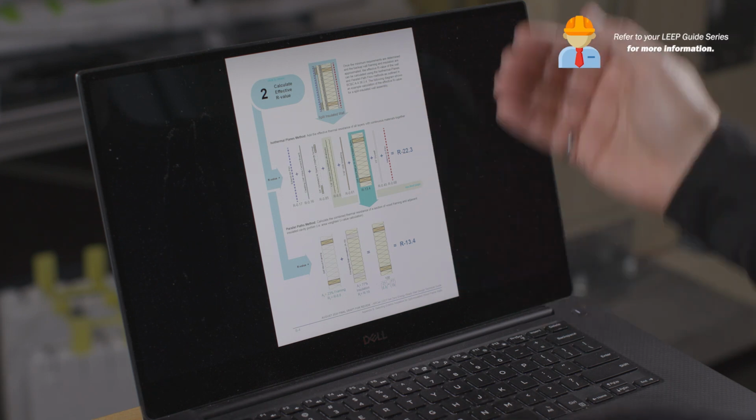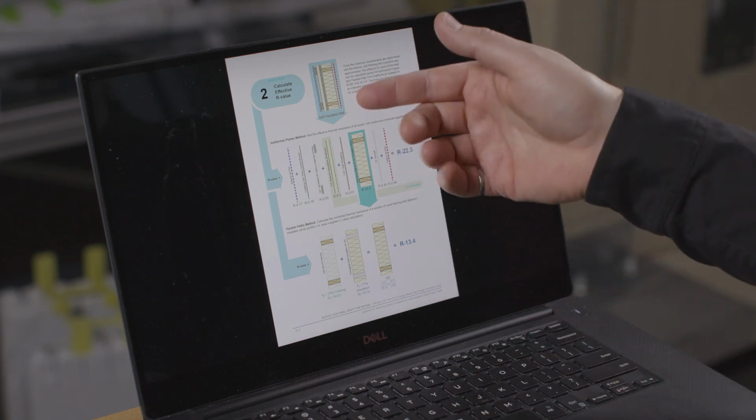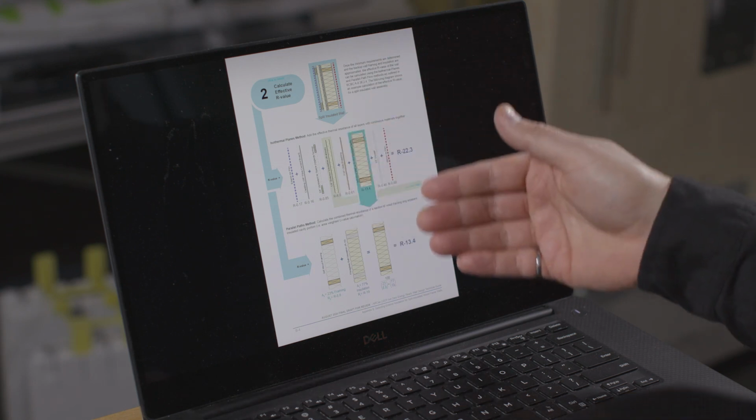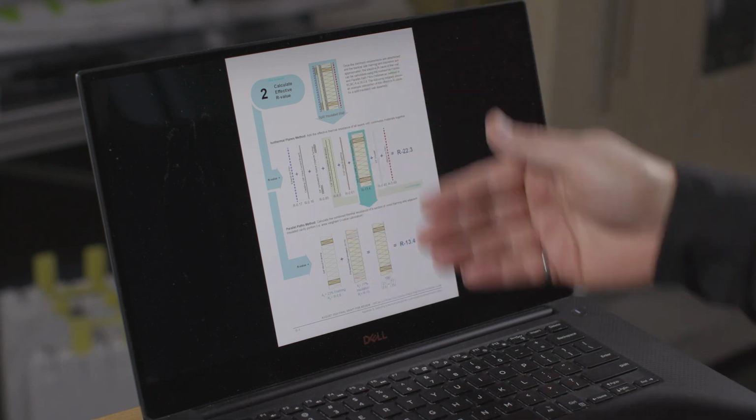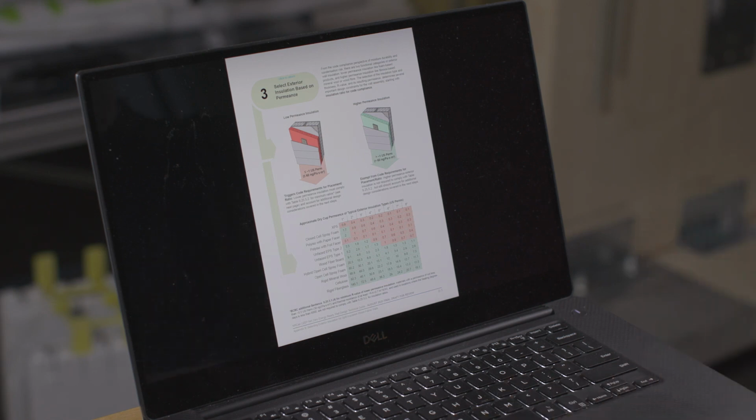Once you've sort of figured out a thickness of exterior insulation you need and type of insulation, you're going to now calculate the effective R value. You're going to use parallel path calculation in 936. You don't have to actually do the calculation here, but this is how it's done, where you've calculated the R value for all the pieces of the R value, including the framing factor, added in with the exterior insulation to figure out your overall R value.